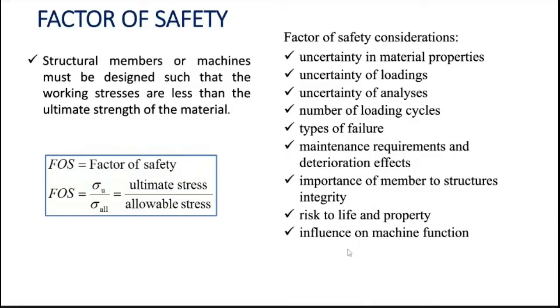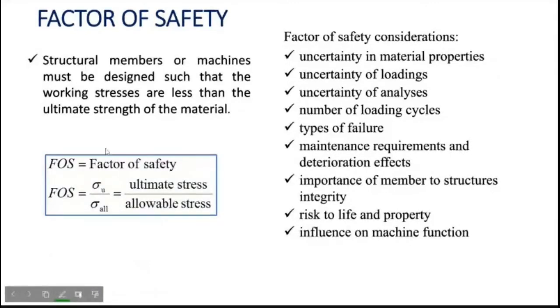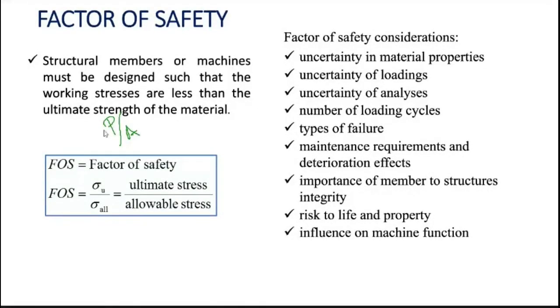If I increase my factor of safety, the dimension of my object will also increase, because stress is force by area. My formula is stress is force by area. I have to reduce my stress, which means I have to increase my area.